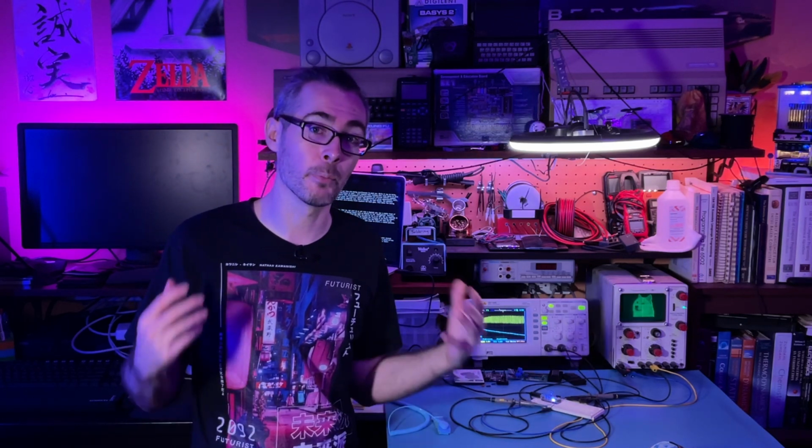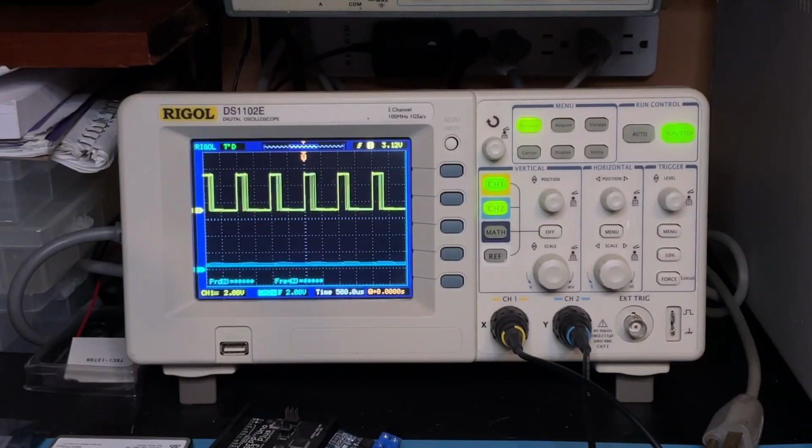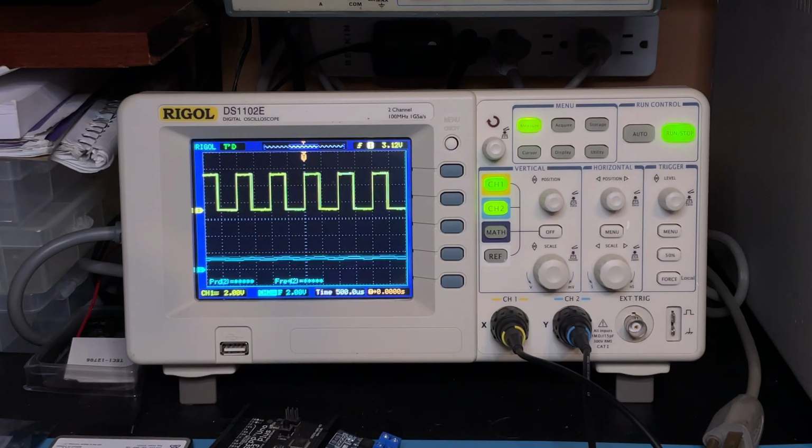That is, not just on or off like a digital pin, but a whole range of voltages proportional to the X and Y positions on the screen. The default way to do analog output on an Arduino is to use the analog write function, which uses a trick called pulse width modulation, or PWM. This uses a regular digital pin that can only be set on or off, but by toggling it on and off rapidly with a timer, and by varying the ratio of the time that it stays high to low, it creates the illusion of an analog signal.